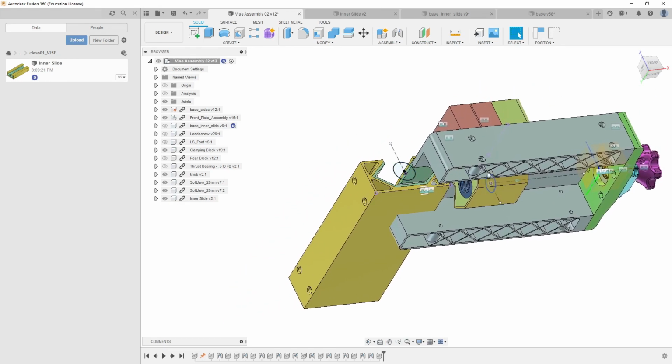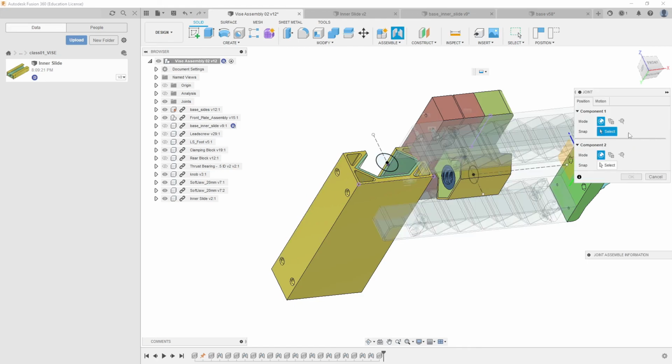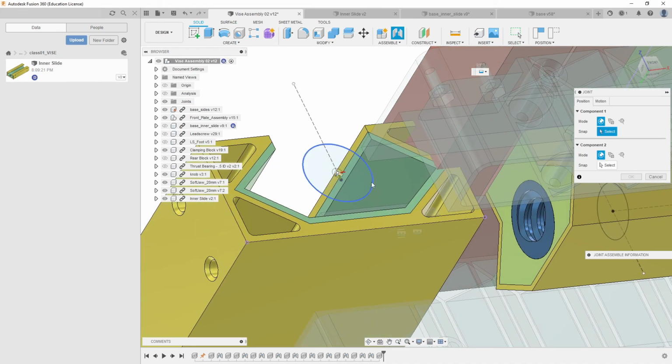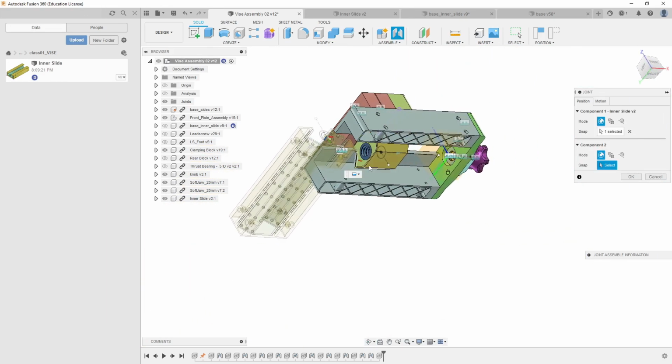And then we can check it in the rest of the context to make sure that everything we did is okay. Based upon measurements that I took as we're going through the lesson here, we've got holes that we place on here. Will they line up? Okay. Well, I hit J for joint. So I hit J and it wants me to select a thing. So I'm going to hit this edge right here. Some secret tricks that we'll talk about later in assembly. I need the center point of that. So I hover over this and it shows there's a center point, but if I move away, it goes away. I hold down Control. Now it doesn't go away, and I can pick that center point. Okay, that's the center of the circle.